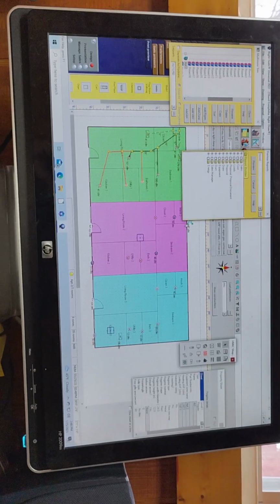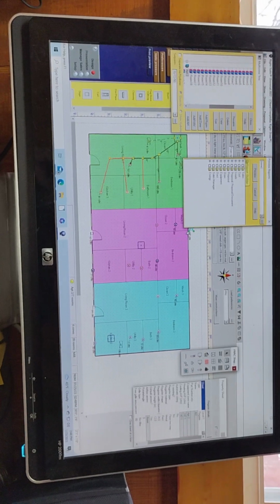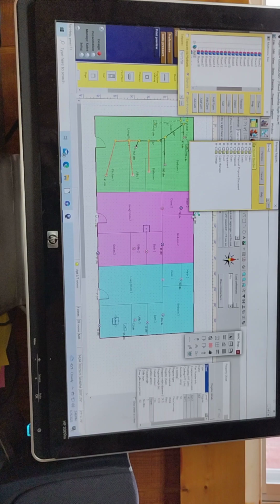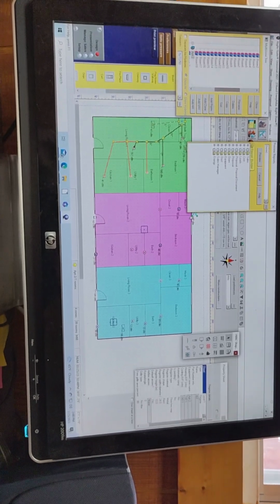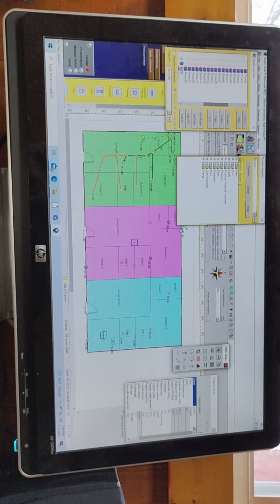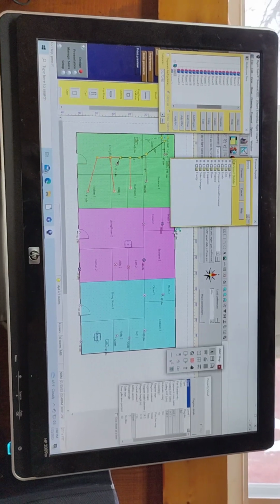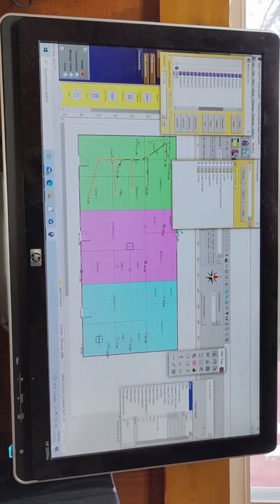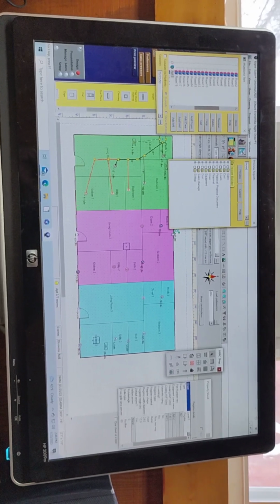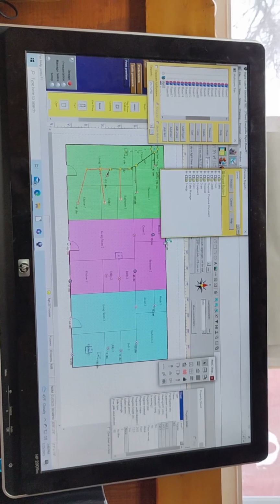We'll evaluate your insulation, everything, while we're there, and basically come up and tell you if your system is oversized or undersized. If you've got a home that seems to keep pretty humid, or you have to turn the AC down to get the humidity out, there's a good chance that you're oversized, which, along with the efficiency and the indoor air quality, is hard on your equipment's lifespan.